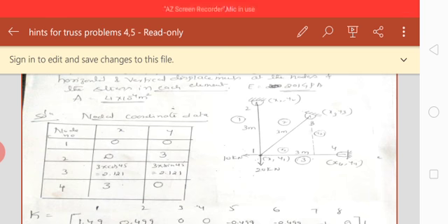Similarly, where is my node 2? Exactly at the top, which is at a 3 meter height from the origin. There x2, y2 are represented, and there I have to represent q3, q4 and f3, f4, because q3, q4 will be 0 since it is completely constrained, and there is no force, that will also be taken as 0. Similarly, now node 3.